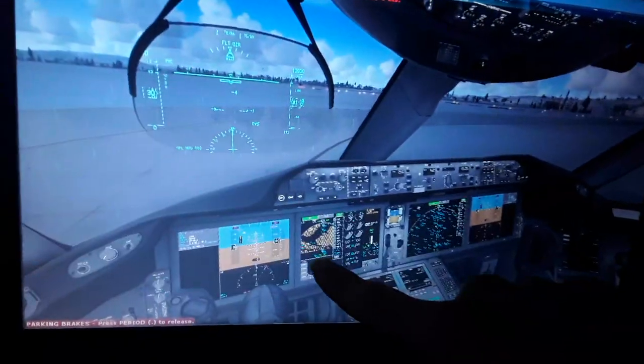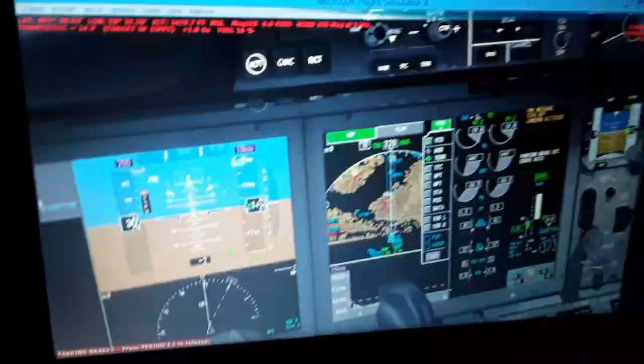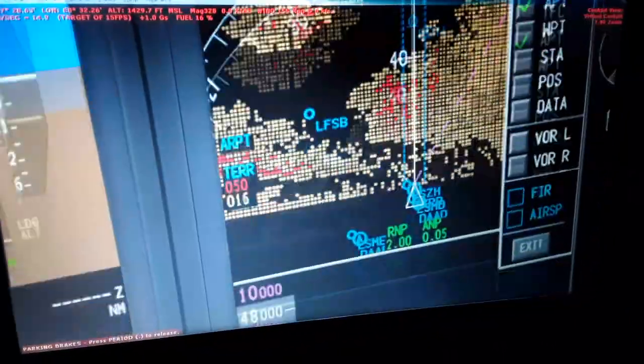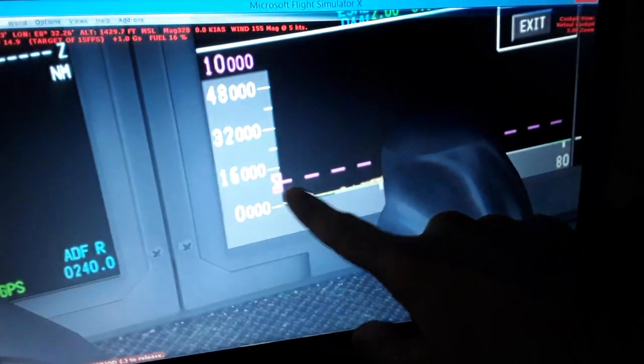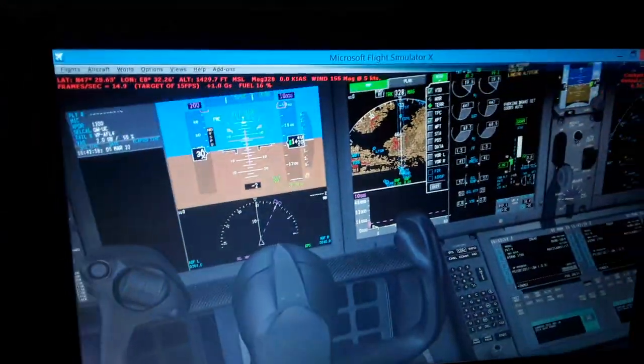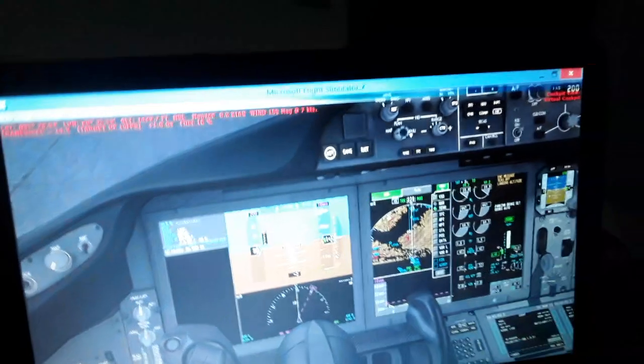If you look in the vertical deviation display, the vertical profile over here, we have the horizontal profile over here of the aircraft, the terrain map, the airports. You can see our own airport, how far above the ground we will be flying. Later you will see also the flight plan in the vertical display. You can see also the airspeed, the barometric altitude over here.